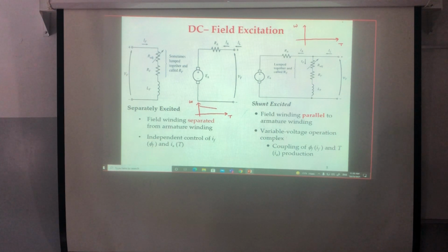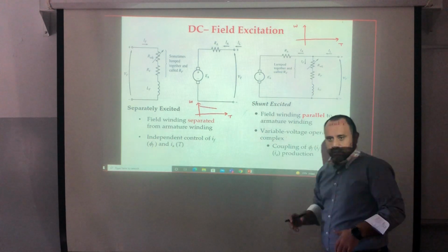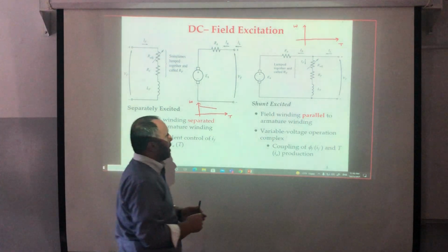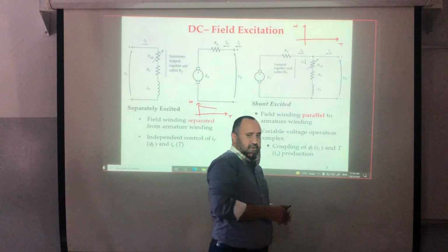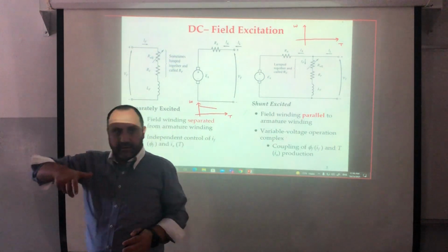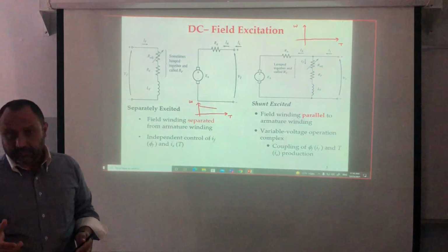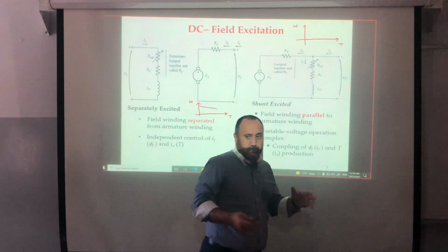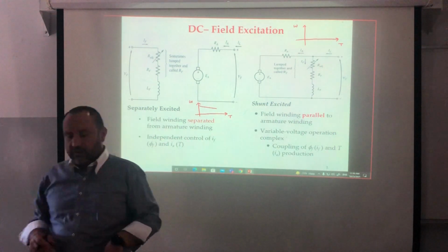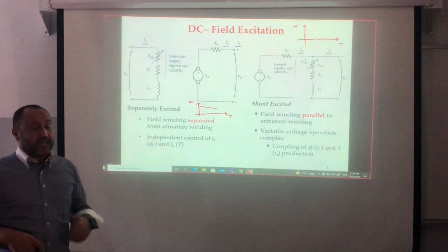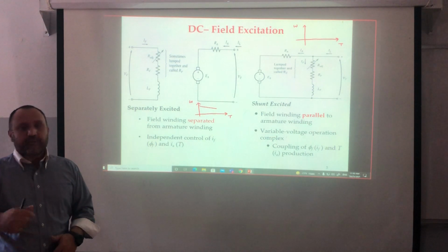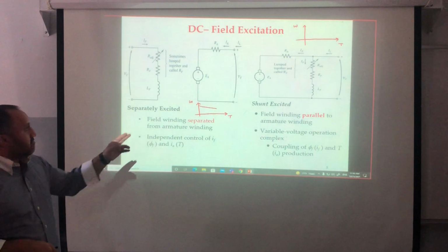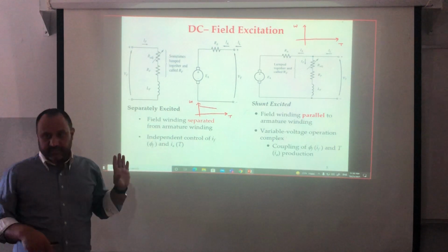Now someone will say, if I need to do that, I need to maintain the field constant, correct? And that's why here sometimes we add some kind of adjustable rheostat or resistance, correct? Because if I'm changing the voltage, I need to maintain the field constant. So someone will say, if I'm neglecting the armature reaction, then the torque speed characteristic will be the same.